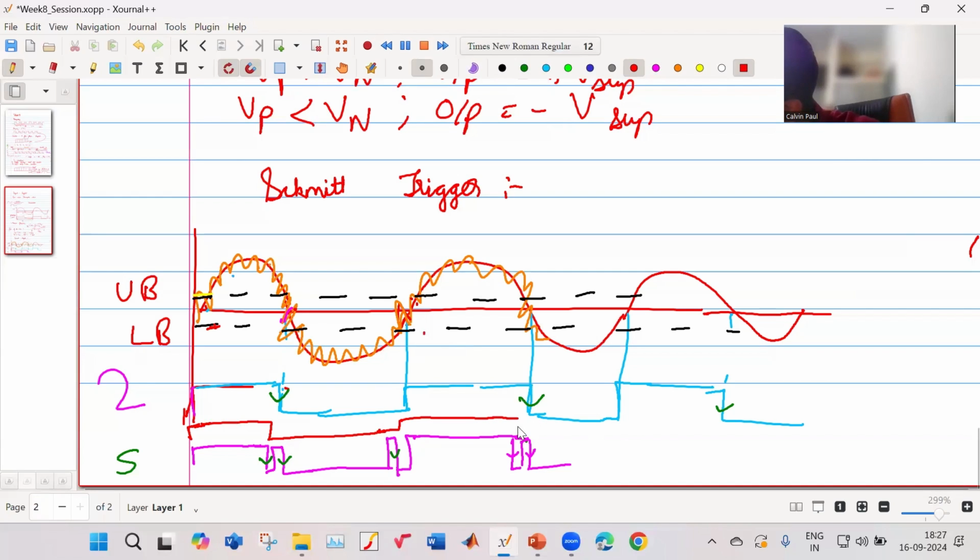Okay. So in this manner, we are getting a signal which has one edge over here, one edge over here. This signal also has 2 edges. So even though there is noise, it has the same frequency as your original signal. And this is because of these bands. These bands are preventing it from changing state, from being very sensitive. Only if it crosses a large value, deviates, then only it is changing. So there is some sort of protection, a certain margin is present.